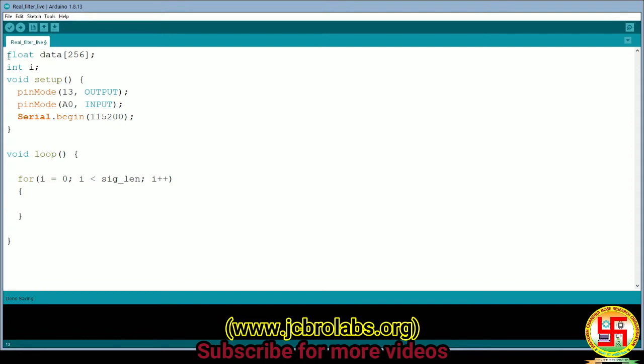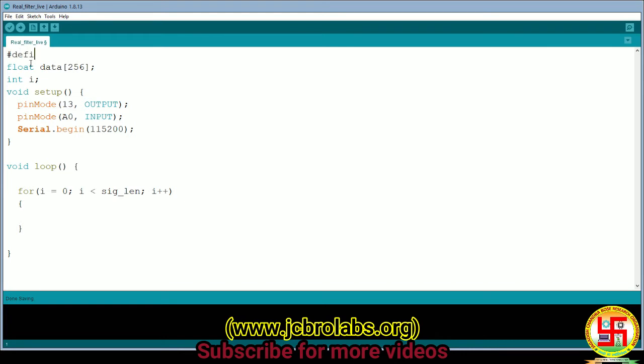Okay, so I know we have to define signal length here as well, so #define SIGNAL_LENGTH 256. Okay, so here we can also define it like signal length 256. Now data of i equals analogRead. So I think we have analogRead A0, yeah, and we will convert it into the corresponding voltage. So we will multiply it by 5.0 and divide by 1024.